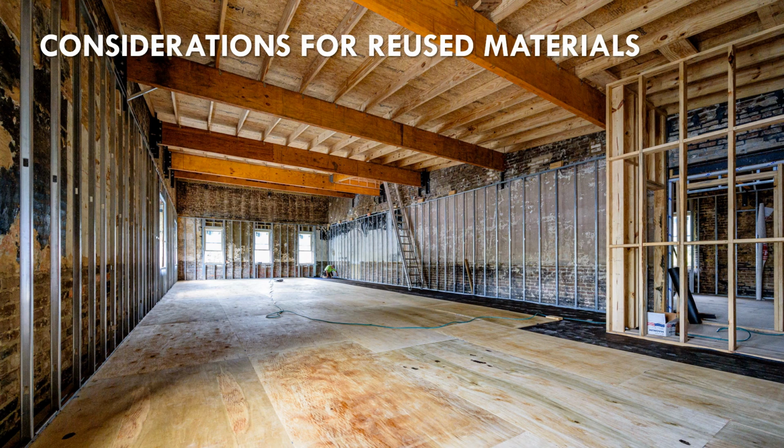Existing buildings may need to adopt a different approach for producing materials passports for the materials already in the building. A pre-demolition, redevelopment, or strip-out audit can identify materials in the existing building. This can be used to gather basic materials passport information and provide guidance on which materials can be reused. There may also be the need to share materials passports with reuse hubs or platforms.